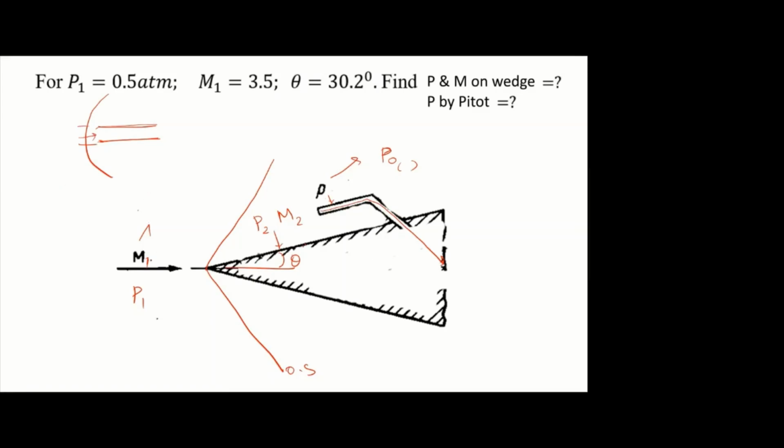So here I have supersonic Mach number 3.5, and the oblique shock wave converts that into a lower supersonic Mach number, maybe 3 or 2.5. So here also it is supersonic flow. Then when it reaches the pitot, there will be another bow shock, and this portion will be a normal shock, right? Now what number will you give it here?